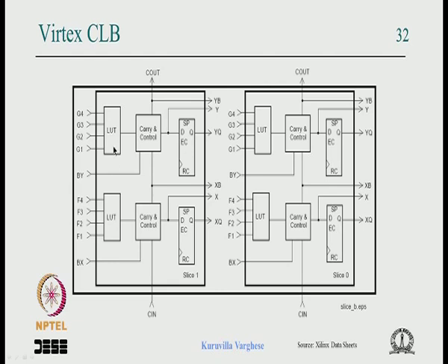So you have, say, a data path with a register, then a combinational circuit and a register, which is implemented like that. Or you have next state logic with an input, and the present state is fed back through the wire, and the next state is loaded to the present state. You get my point. So that is what it offers.